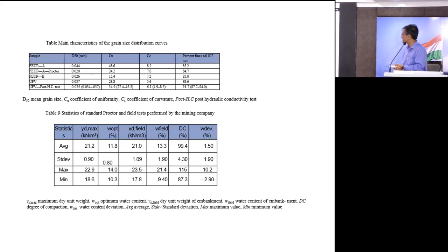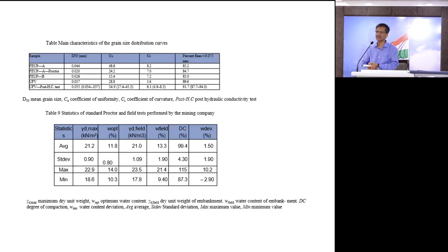Why this value is less or more, the optimum content will depend upon that, that is one aspect. This also I want to make clear: for a higher granular size, the optimum content should be less. But we also found that some industrial wastes like bauxite residue have internal pores, so they absorb more water than required. That aspect is not there in natural sand. Natural sand cannot absorb more than what is required for workability, but industrial waste can also suck some of the water into its void space.